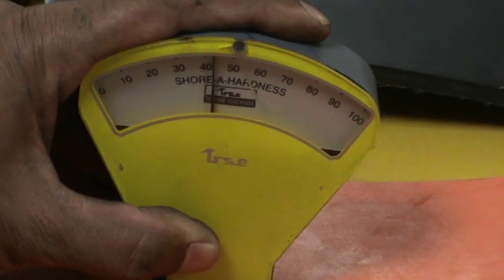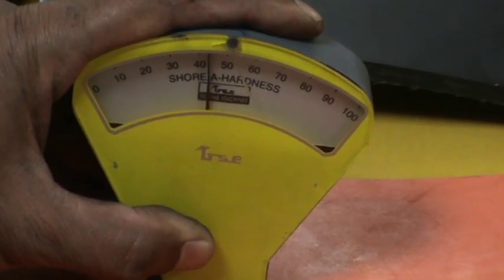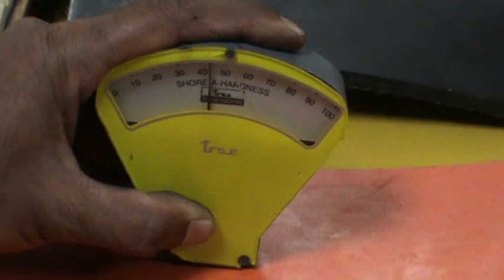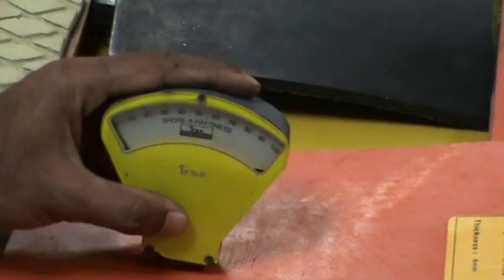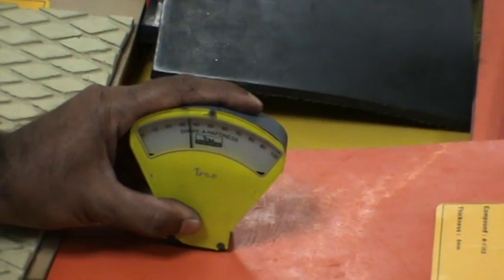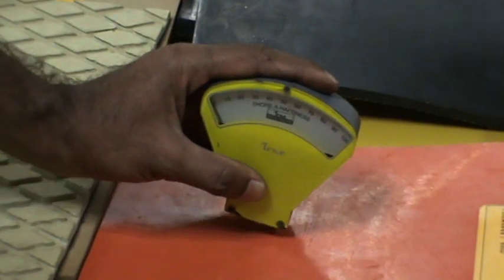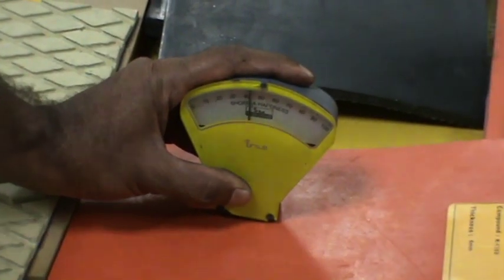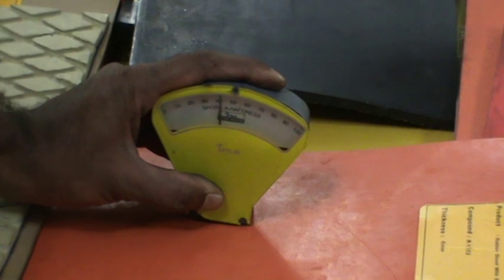The recorded result is usually specified to have a plus or minus tolerance, since the reading will vary across the surface of the product. In applications of high impact areas, it is desirable to have 60 Shore-A hardness, whereas in applications such as rubber lining, it is common to use 40 Shore-A.